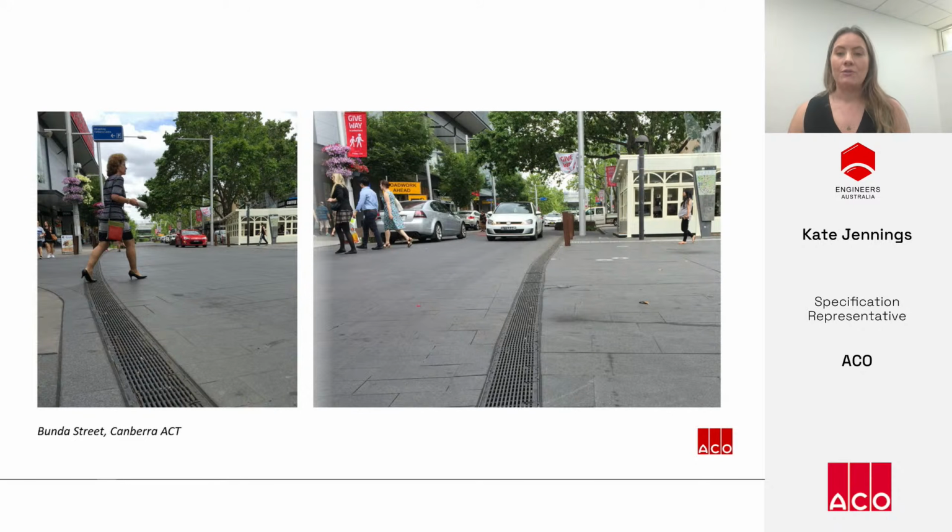Bunda Street in Canberra is a commercial and shopping precinct. In this shared space, vehicles give way to pedestrians at designated road crossings. Graded trench drains were used to outline the extent of the road, but also to intercept the runoff from pedestrian areas.